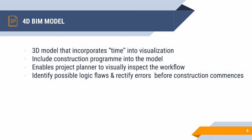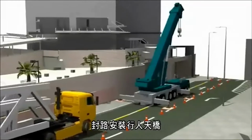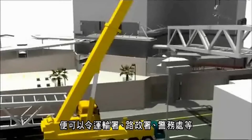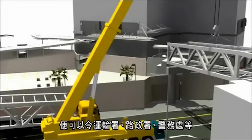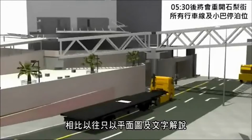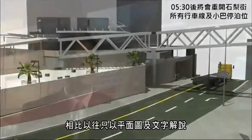A four-dimensional BIM model is a 3D model that also incorporates time in the visualization, where the construction program is included into the model, linking all building components to the scheduled construction sequences. This enables the project planner to visually inspect the workflow, allowing a simpler process when identifying possible logical flaws in the program, rectifying these errors before construction commences, ultimately reducing risk.